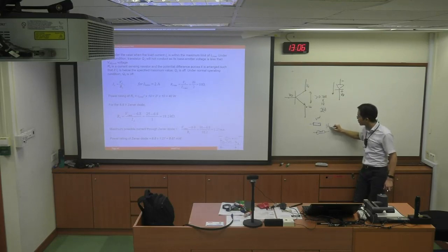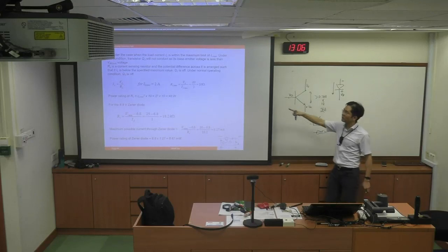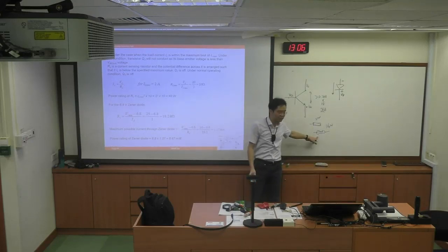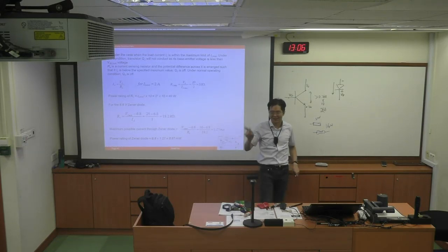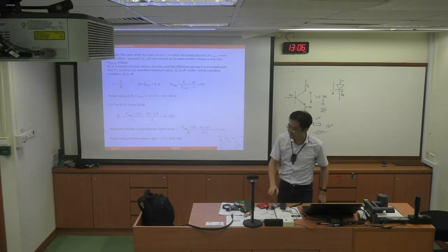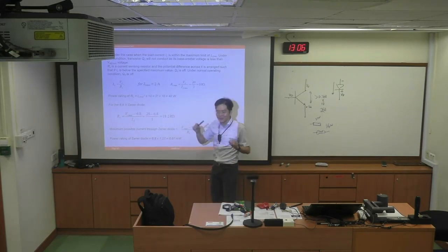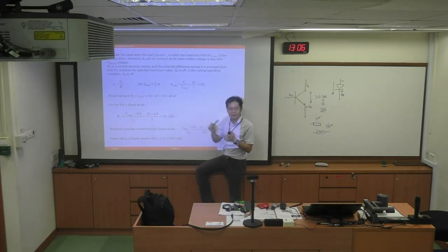This is typically 1/4 watt maximum, 250 milliwatt. If you put this load resistance with a nominal 1/4 watt rating resistor, it'll literally blow up. So be careful with that. This is why checking today's lecture and doing the power rating for your lab calculation is also important.